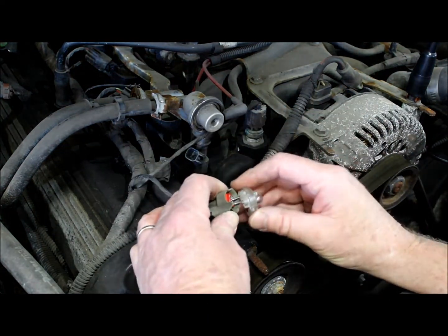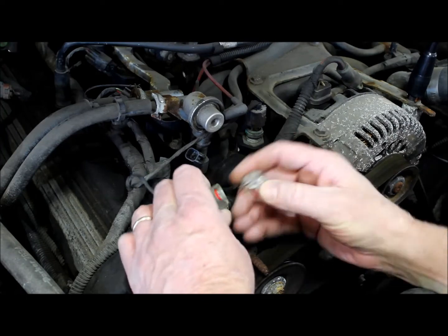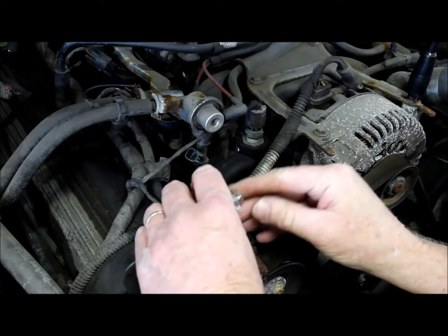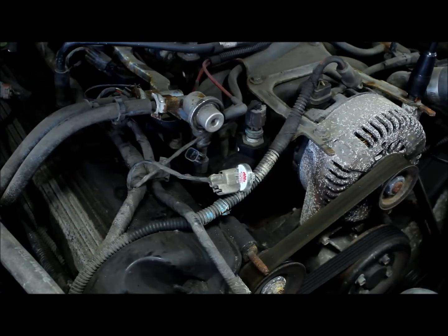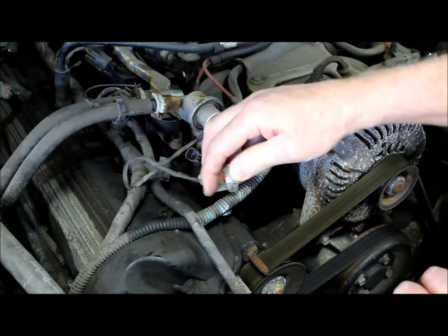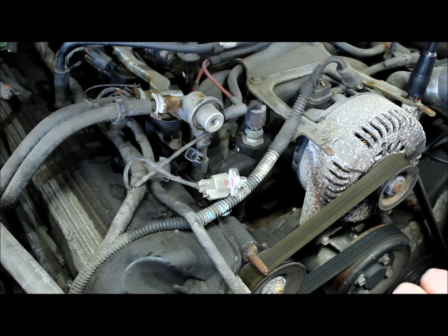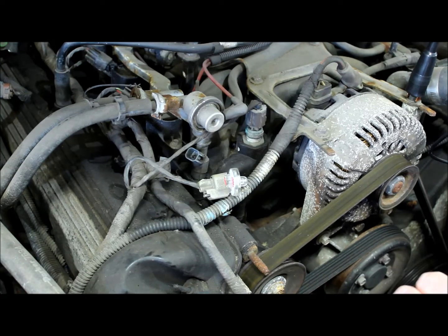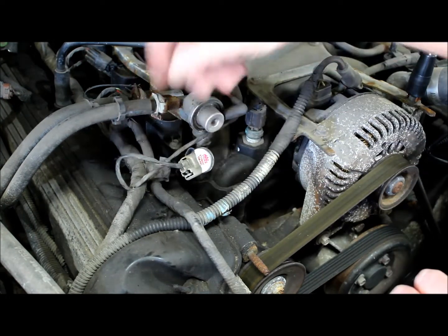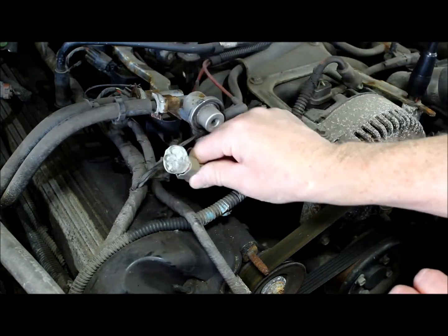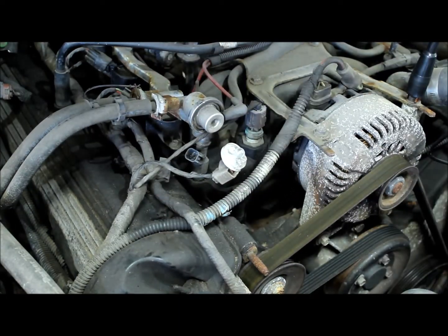A Noid light just basically replaces the fuel injector in the vehicle and allows us to see that it's getting both power and ground. Now when I start the vehicle, this is going to start to flash. I don't know if the camera is going to be able to keep up with the flash rate of this injector. So just get it where you can see it well, and we'll see what happens.